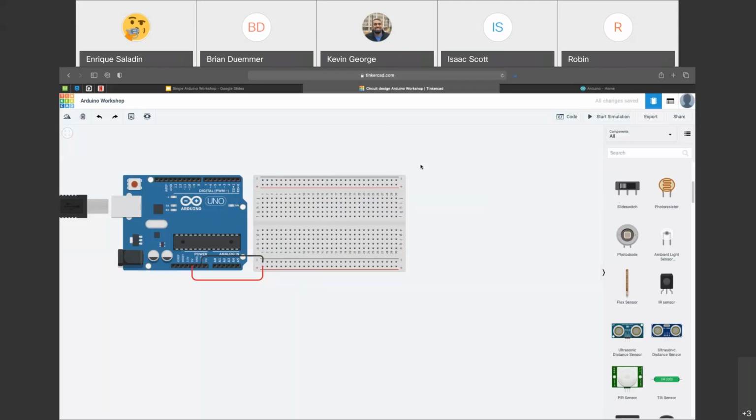So those are available. Going back to Tinkercad, I'm going to start by having my Arduino here on the left side. I have a breadboard here. On the breadboard, we can simply socket components, and we can get started with our first circuit. I have the 5 volts coming off the power, and I have the ground coming into the ground of our power rails. That way we can easily hook different components up without occupying different 5 volt lines.